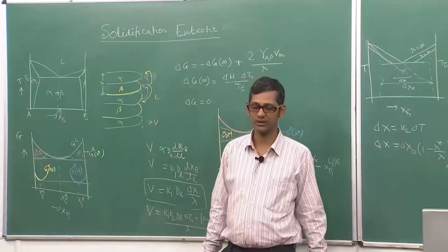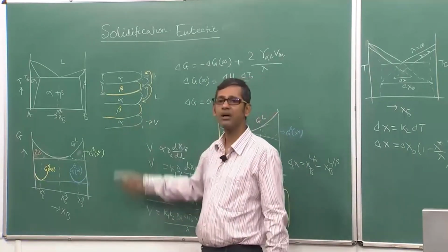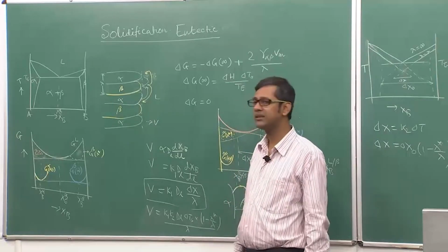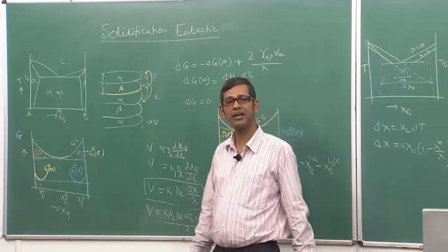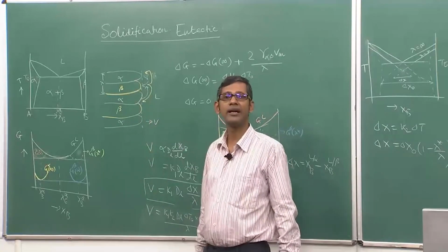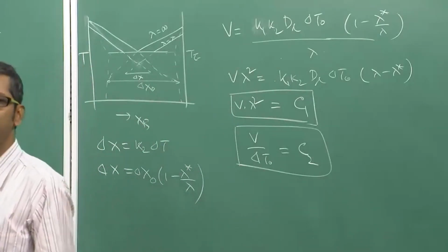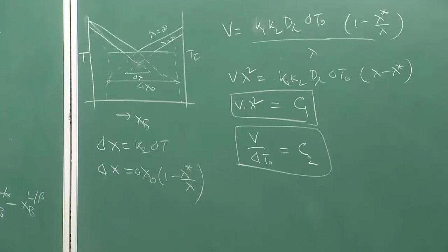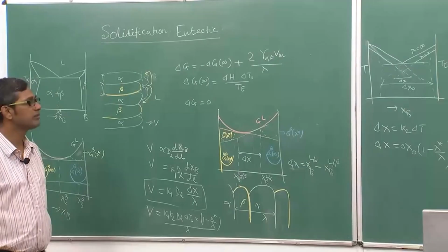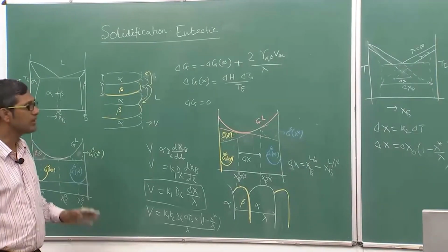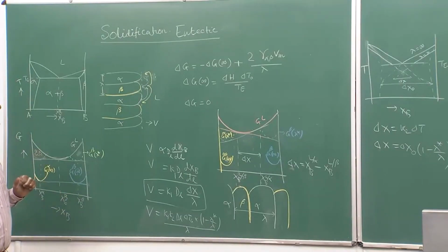Or calculate it using this equation. A better method is to take a system in which we can actually observe the eutectic growing at a certain velocity, observe these lamellae, and measure the value of lambda perfectly when it is in contact with the liquid. Then use that value at a particular level of undercooling to calculate v. So finally, it boils down to the important aspect that eutectic growth is still not a fully solved problem. It is a nondeterministic problem in the solidification literature.